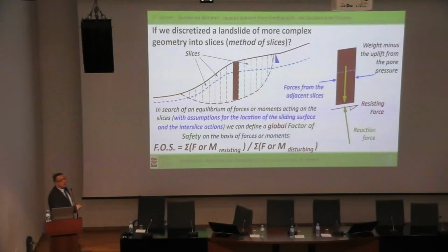and we formulate our equilibrium equations that eventually lead, as George Gazzetta said before and we like to use, to a total factor of safety that is practically the ratio between the sum of resisting forces of moments over the sum of driving forces of moments. And just a comment on the partial factors, too many times, if we use the partial factors, we will